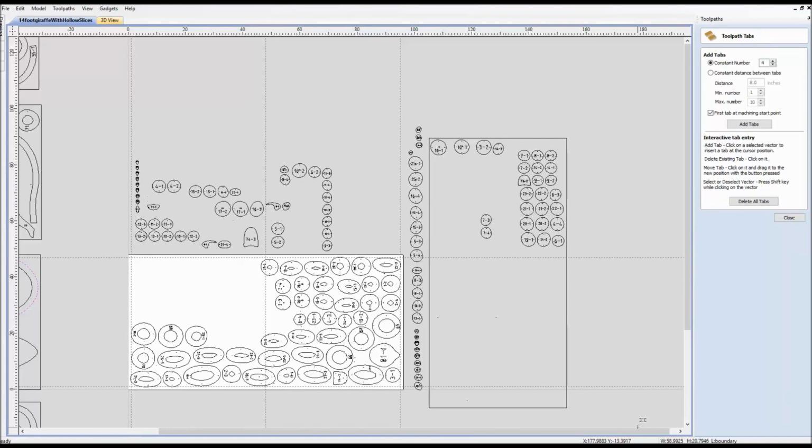We've looked into the world of tabs or bridges today, whatever you want to refer to them as, how to add them, the different sizes of them, locations, where to look out for putting them as far as how it's going to affect your cut, whether it's a cleanup process that you're going to have to deal with, taking away the strength of the scrap material, the ease of cutting them out afterwards. Think about the post cleanup that you're going to have to do when using the tabs.